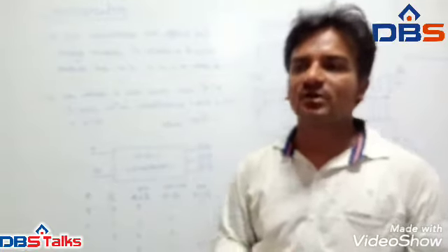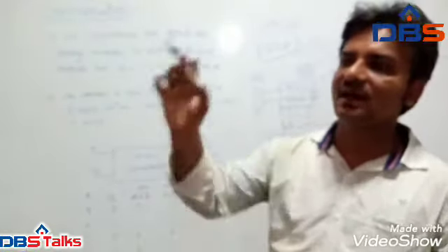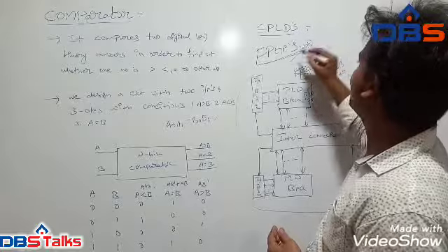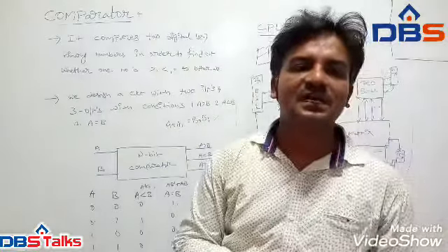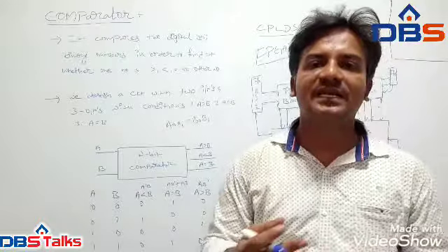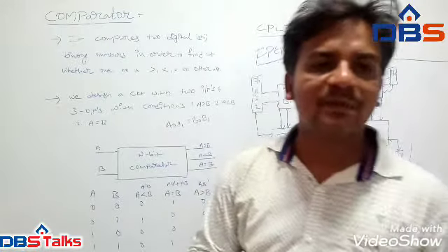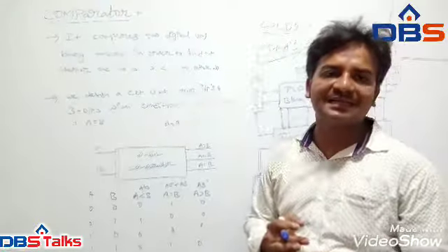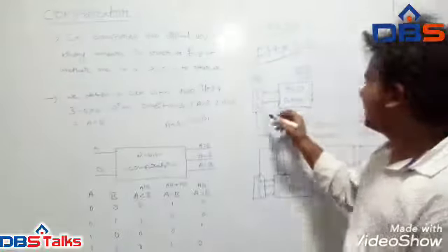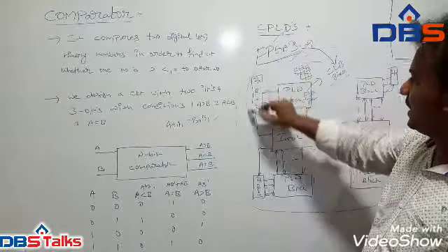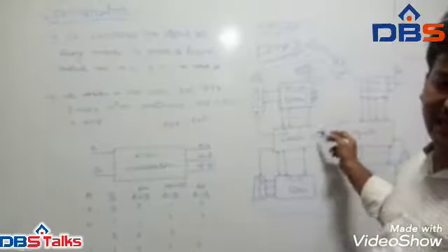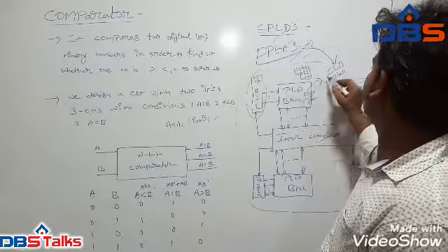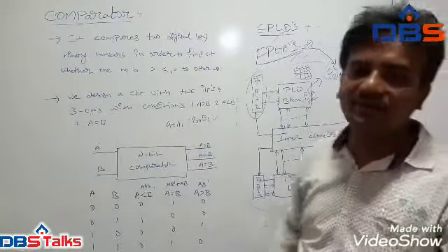So if you want to implement a heavy or long logic function, at that time we prefer field programmable gate arrays. Because it has three configurable blocks, that is the CLB (configurable logic block), the input/output block, and interconnection switches. As a CPLD consists of IO and an interconnection matrix, an FPGA also consists of the same fields, but it may differ. The FPGA consists of configurable logic blocks.